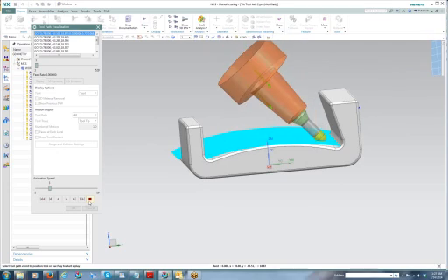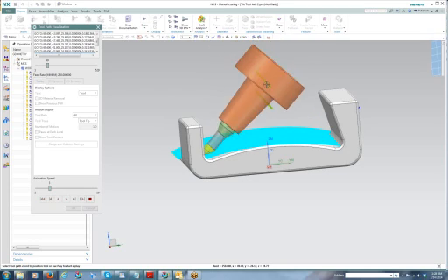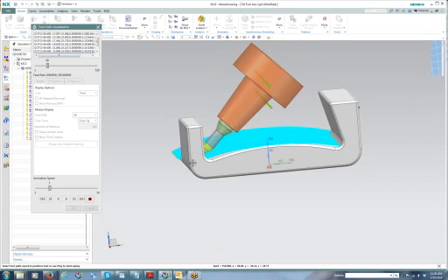What's the advantage of doing that? Well, often 5-axis machine tools are limited by the speed of the rotary axes. So if we came out of this little waterfall area and then did the rotation all at once, it would slow the tool down through this area. What we want to do is create a fan where the rotation occurs over a much larger area of the toolpath. And that's what we're doing here with the tilt tool axis and our hinge point. We're giving you the most efficient toolpath possible by fanning over this wide area.